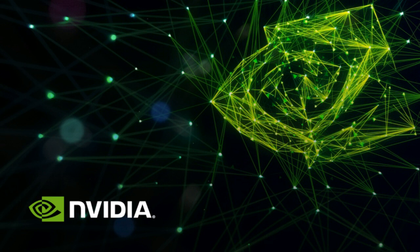The nice thing about these models is that you can use the TensorFlow object detection API to train them for your own tasks. If you make your own dataset with a bunch of bounding boxes, you could train on it, and you'd have to use one of those model architectures for the tools we have in the JetBot project. But if you use one of those architectures, you could train it to detect whatever bounding box you want, and then you can get basically 14 or 18 FPS depending on which model you're using on the Jetson Nano.